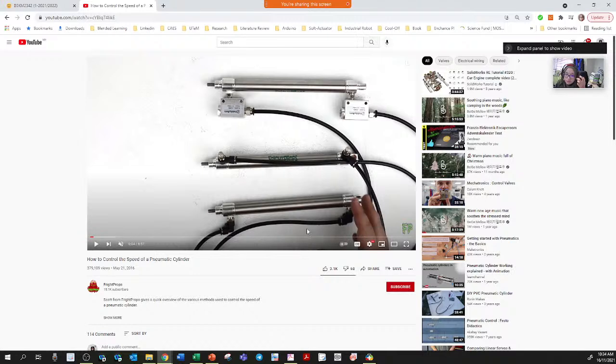Okay, the first one, if you look at the down part, is that he only has the pneumatic actuator, which is connected to the airflow. So by doing that he controls only the air pressure from the valve, giving 0101 basically, and then the pneumatic actuator will extend and retract. That one is the first one. But you cannot really control the speed of the extending of the piston.